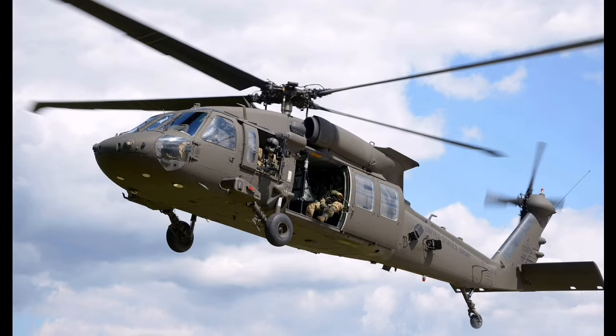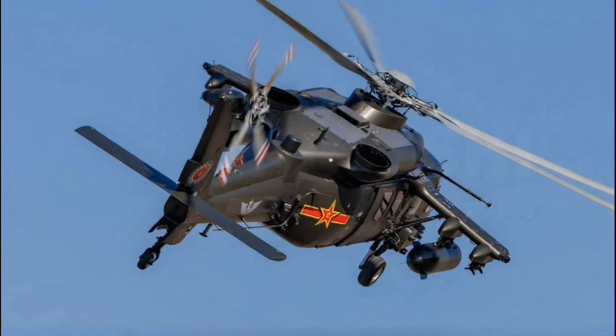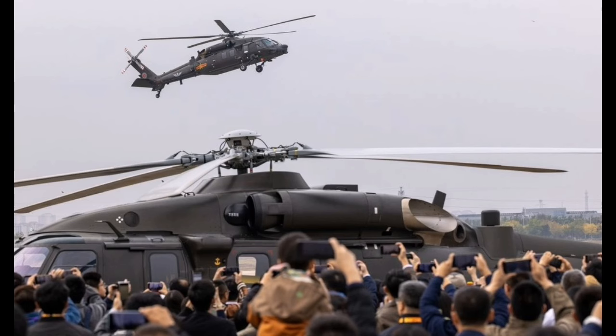The tail rotor is a 4-blade design that is canted at a specific angle, which serves a dual purpose, providing the necessary anti-torque control and contributing a small but measurable amount of vertical lift, which improves the overall efficiency of the aircraft. A fundamental engineering requirement for the platform, inherited and further refined in the T variant, is its capability